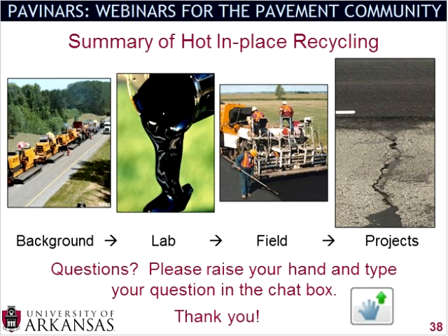And then Mark has a question: is joint sealant bleed through an issue for thin depths? And that's also a very good question. You saw in some of these pictures, in fact here on the right, if you can imagine above the project section, if that has joint sealant in it and you only go maybe half the way down or two-thirds of the way down into that layer and there's joint sealant down there, I haven't read anything about it being an issue per se. But just like putting a typical hot mix asphalt or warm mix asphalt overlay on top of something like a joint sealant, I do think that is something that you need to be aware of.